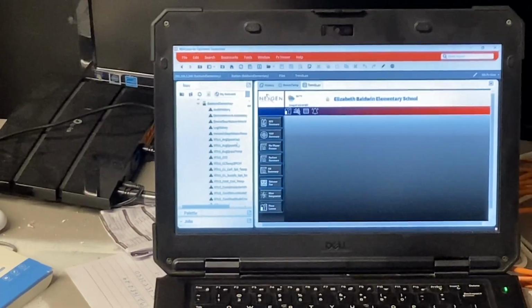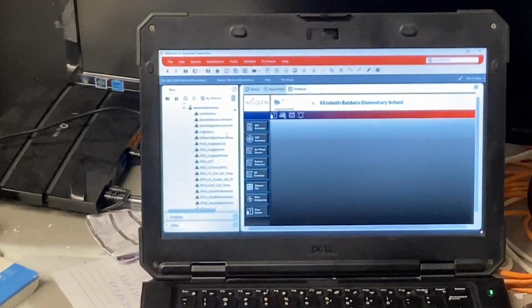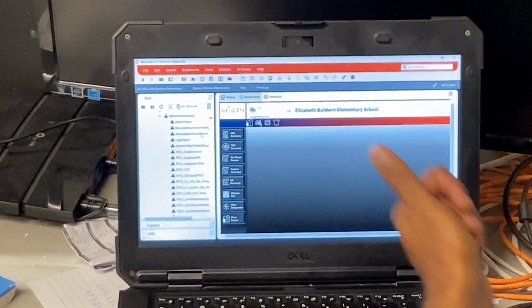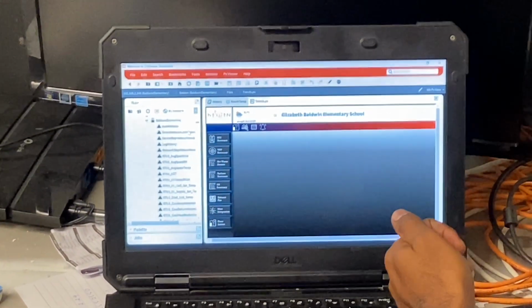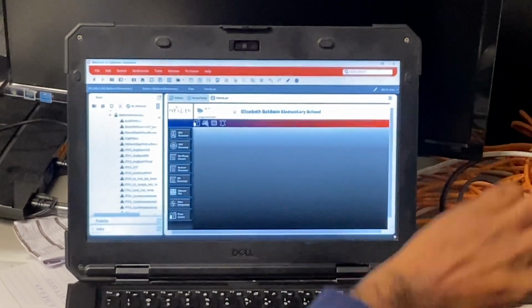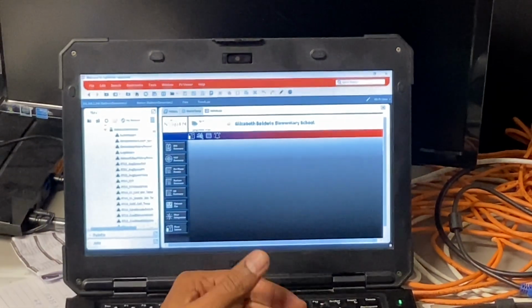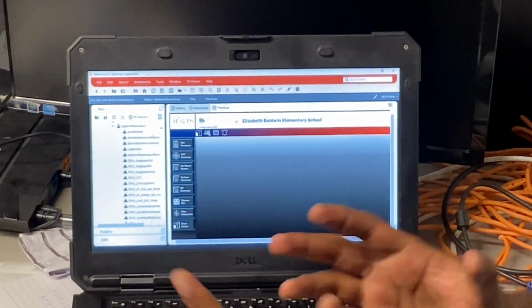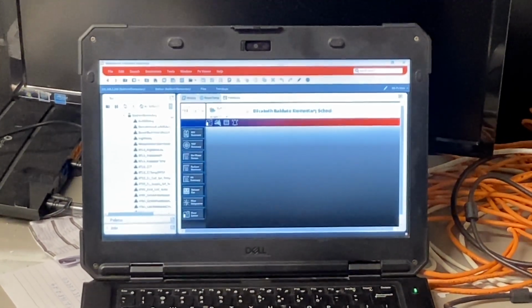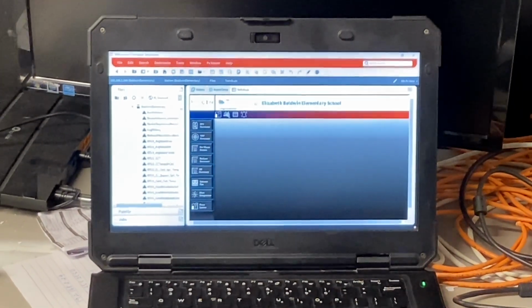And the other stuff I forgot about, VAV. Sorry, I'm going back to the VAV. The occupancy sensor integration is in progress. We are integrating to the lighting panel, so they give me the occupancy sensor status from each room. Based on that motion sensor status, I override my effective schedule.